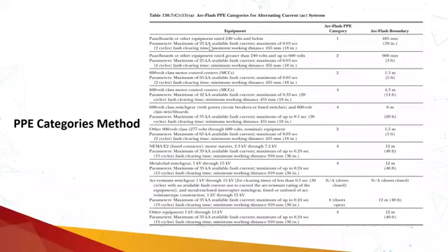In my industry, if the maximum available fault current is 20 kiloampere, I can use it because 20 kiloampere is within that 25 kiloampere maximum value. My device clearance time is 0.03 second. I can use it. If my device clearance time is less than 0.03 seconds, I can also use it.